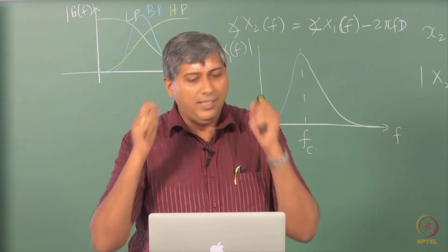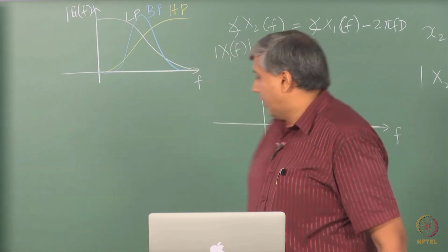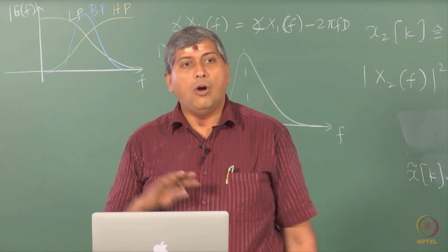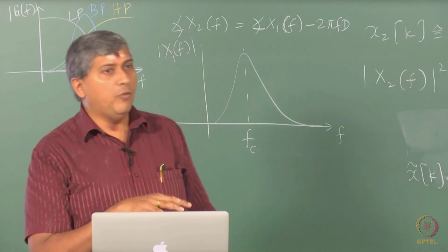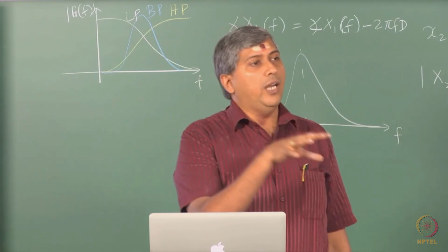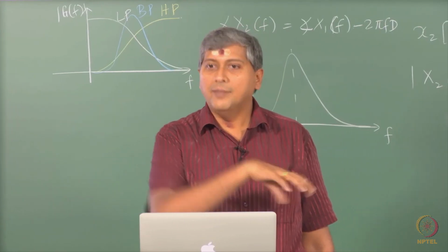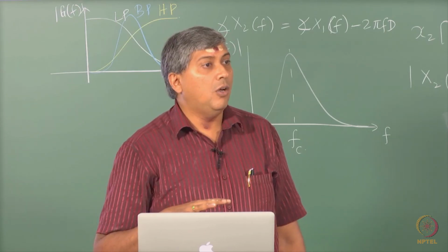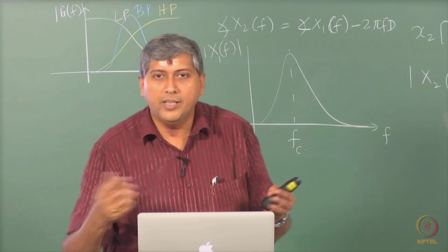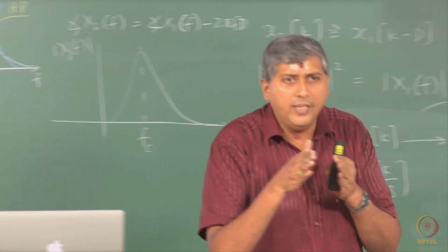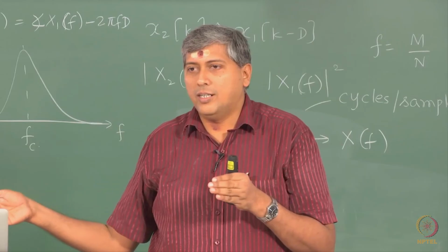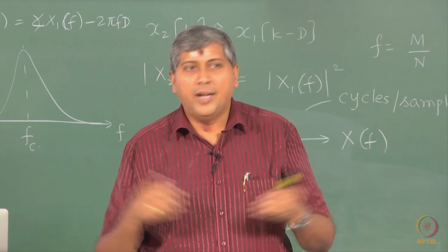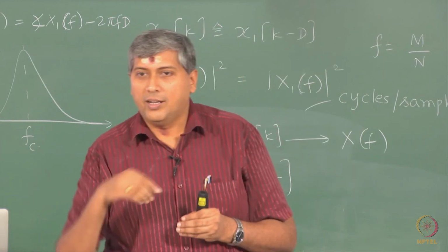Using this simple slide, really you can understand how wavelet transforms are used. Essentially, you can think of wavelets as functions or filters. Even in Fourier transforms, you can think of the Fourier transform as a decomposition of the signal onto a space of sinusoidal functions, or you can think of it as filtering. What you are doing is, you are taking the signal and passing it through a filter. This is not the Fourier atom. How would the Fourier atom look? It is a sine wave. And how would its frequency response look?